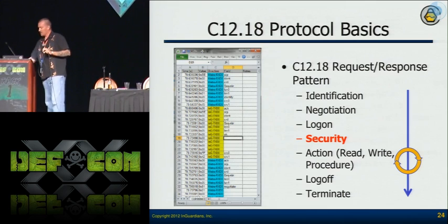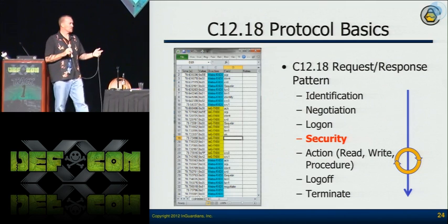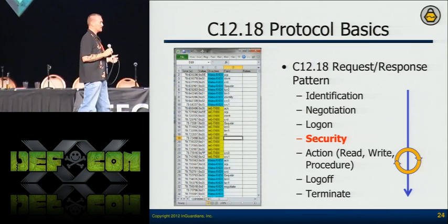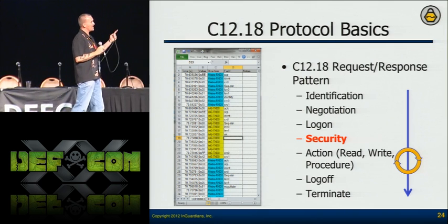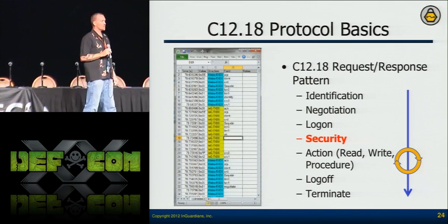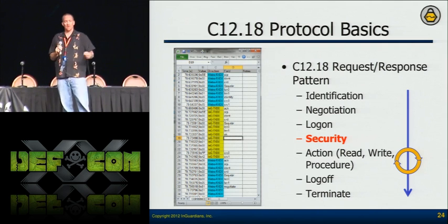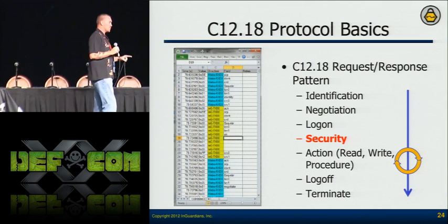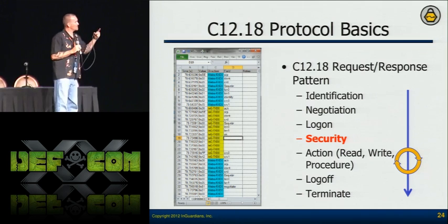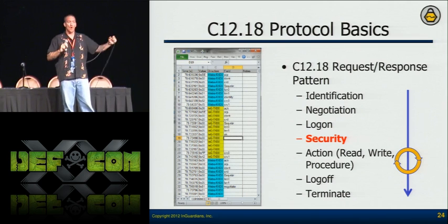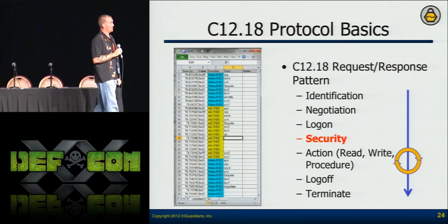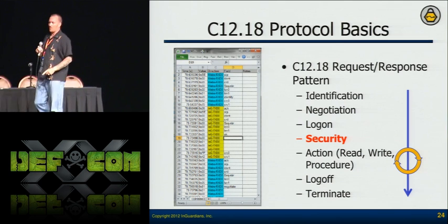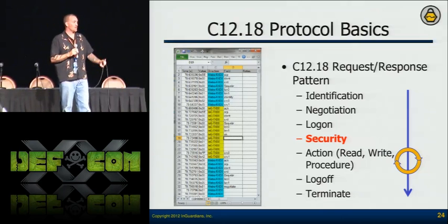What's great is, then I merge the files, because you export the receive pin, then you export the transmit pin, and you can merge these files. Now you can see the full conversation, the request and response, the NIC card logging in, the metrology board saying okay, so identification, negotiation, log on, security. Woohoo! That's a security code. Now I know how to log in. And if they're using that code for the optical port, that's what I'm hoping.